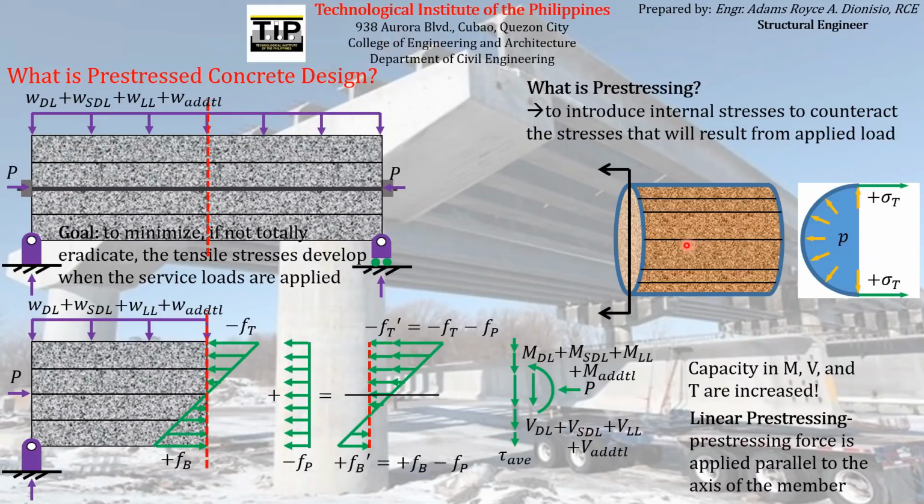So once they break, the water will leak. So one way to further strengthen this wooden stave is to put a prestressing force on it, for example, by adding what we call a steel band. If we look at that steel band here, it will look something like this.